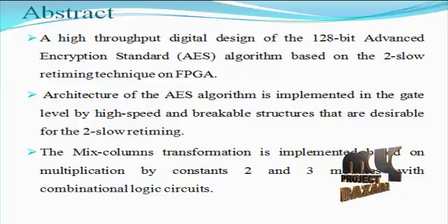Over the last few years, AES encryption has been used in many cryptography applications. Several techniques have been proposed for implementation of the AES algorithm on FPGA. The AES algorithm is implemented using different methods and contributions, which can be characterized as follows. In the first category, pipelining, sub-pipelining and loop unrolling techniques are used to increase the operational frequency and throughput. The second category includes the design of lookup tables and the implementation of the byte substitution block, meaning the S-box functions in our process.